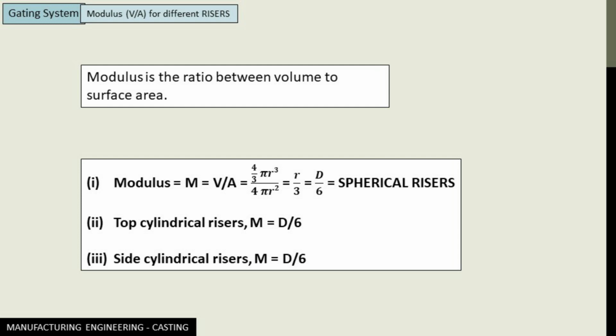Prior to understanding the methods of riser design, we need to understand something that is called modulus of riser. Now the modulus is the ratio between the volume to the surface area. So let's take an example of spherical risers.